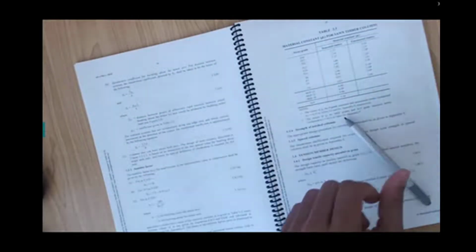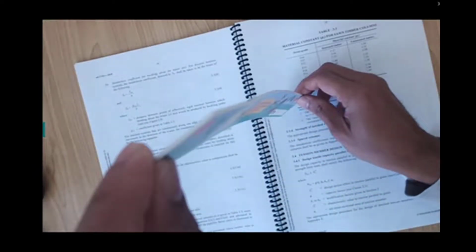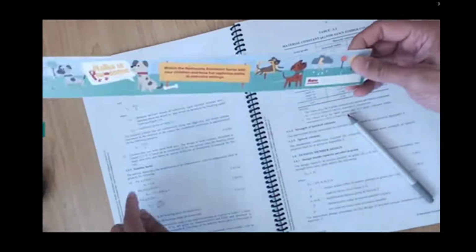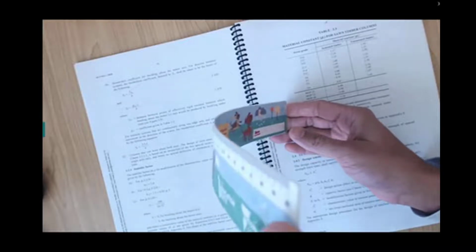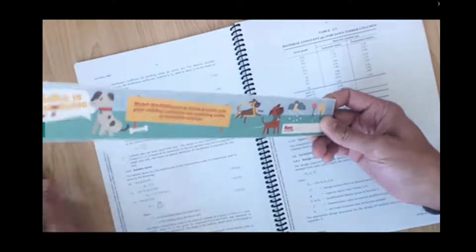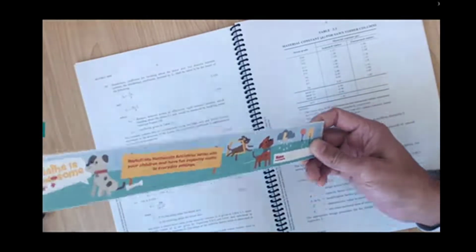Now that is for columns, meaning that if you have a column like this, vertical, and if I do this, it does this. Look at that, it does this. So if you have a short column, it will not do this global buckling. This is called global buckling, or a stability issue. This is the intermediate column, and this is quite a long column.